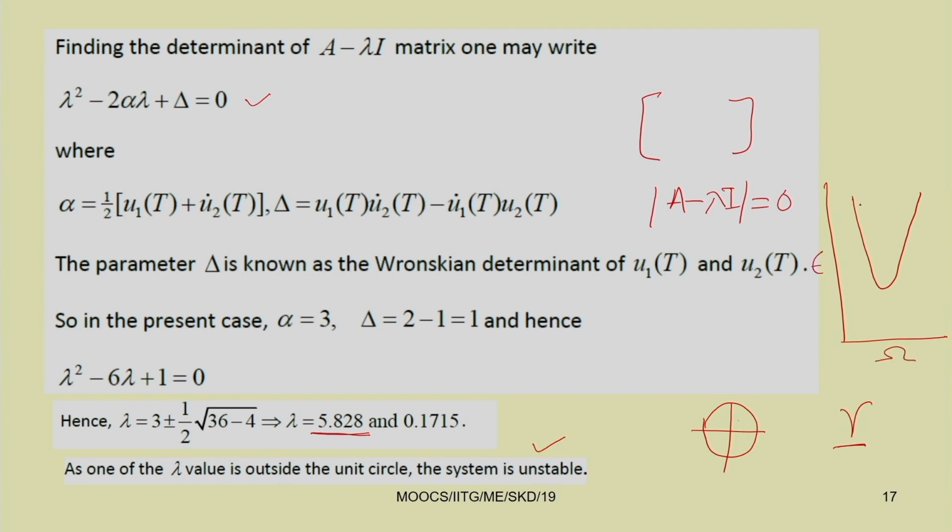This boundary is known as the parametric instability boundary or transition curve, and we can find the minimum value. For example, here you can find the minimum value of epsilon for which the system is always stable. This way we can study different boundaries or transition curves for different equations of parametrically excited systems.